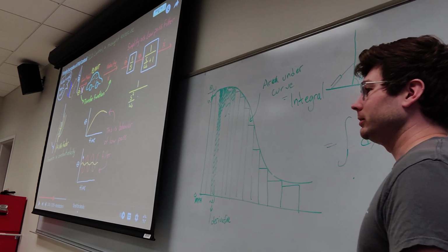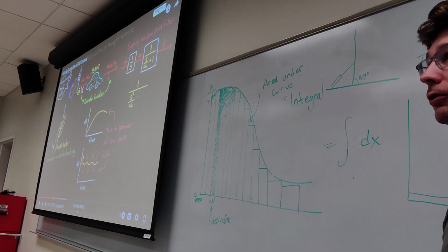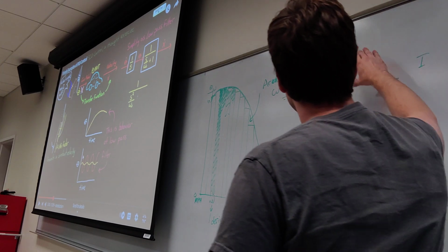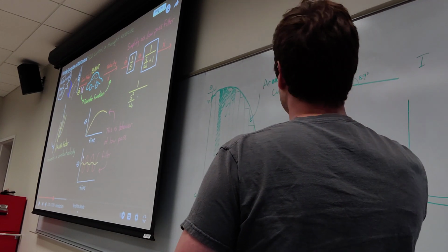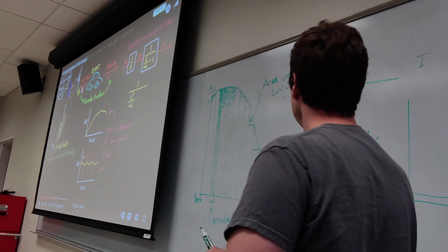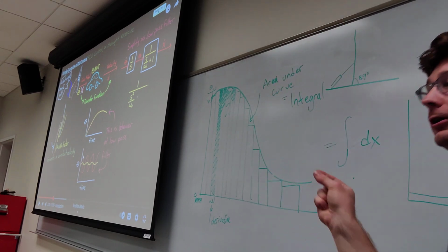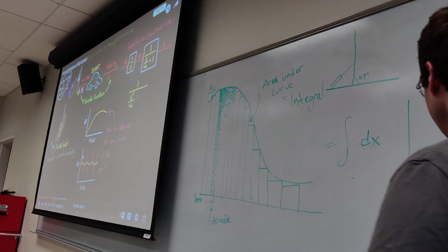We're at 89 degrees all the time. We're constantly off by 1 degree. But our control system isn't responding strongly enough to overcorrect, right? It's just that the amount it's responding is enough to get it to 89. It can't quite bridge the gap. It's not quite different enough to get the extra nudge that it needs.